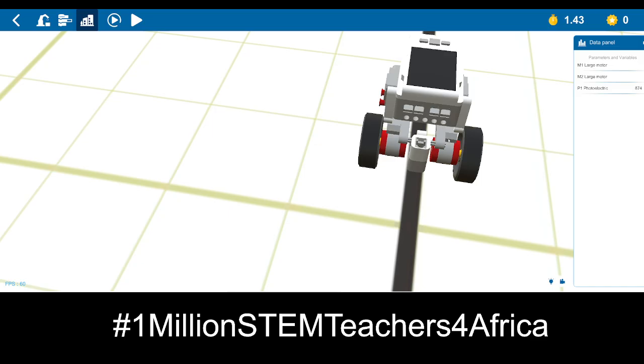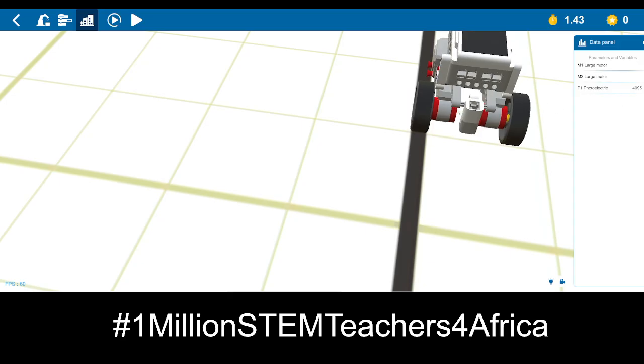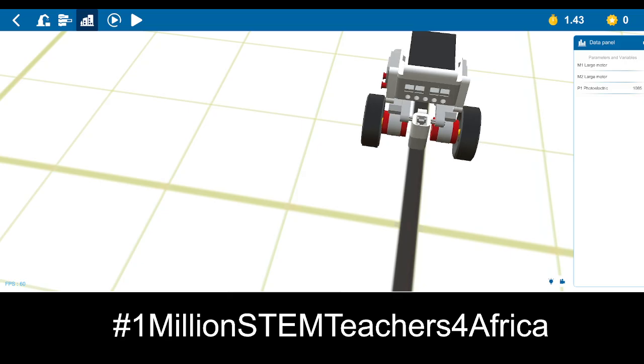Okay? Here, we are getting a very huge value because look at the analog values. It's huge because we are receiving back a lot of light. But here, it's very, very small because we are receiving a very small quantity of light. Now, on the digital value, we are getting 1 because this is a black line.